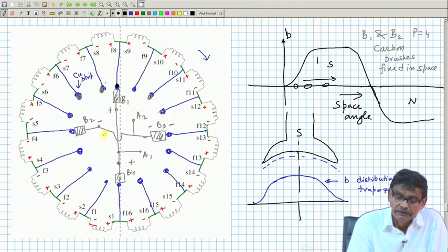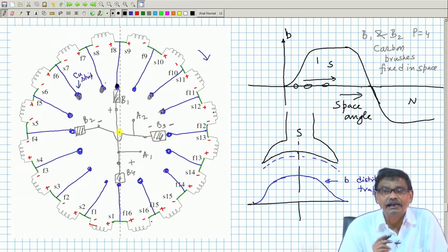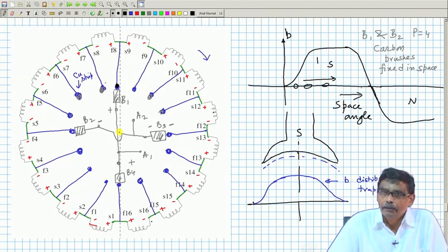Okay. So, here is one parallel path, here is another parallel path. Similarly, from this positive terminal, if you want to reach the negative, you see 4 coils, you reach the negative. From this another 4 coils, you reach the negative. Therefore, between the positive and negative brushes, the armature circuit, all the coils will be divided into as many parallel paths as the number of poles of the machine, provided it is a lap winding at least, because I have not discussed anything about wave winding, that I will do slightly later.